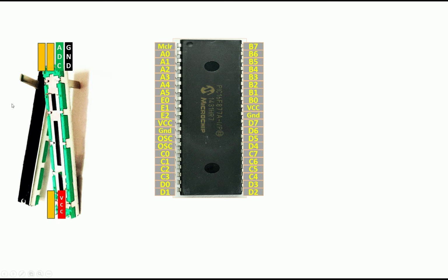And the rest of these 3 pins, the 2 of the 4 pins on the left side of the top, and the one at the bottom left, leave them not connected. So these are the not connected pins, the orange ones. So right now, first we will connect them. We connect the ground pin directly to the ground of the PIC like this.